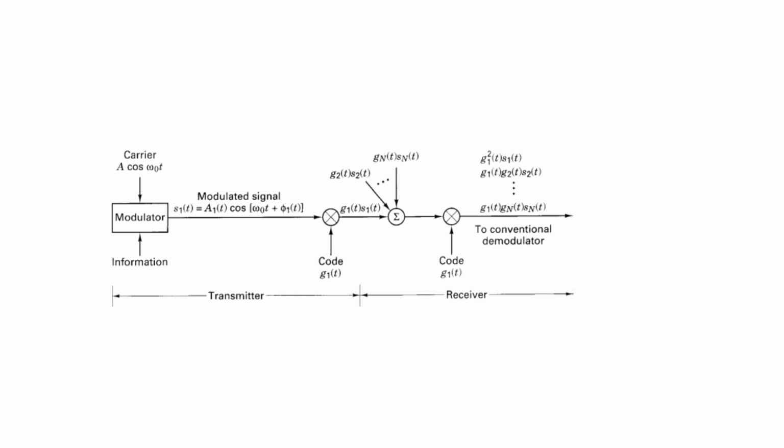At the receiving side, the signal along with the noise is received, and it is despread by using the same code. Whatever sequence is generated by the PN sequence generator at the transmitting end, the same code word is generated at the receiving end, and the received signal is multiplied by the PN sequence signal, so that the signal is despread, and next it is given to the decoder.